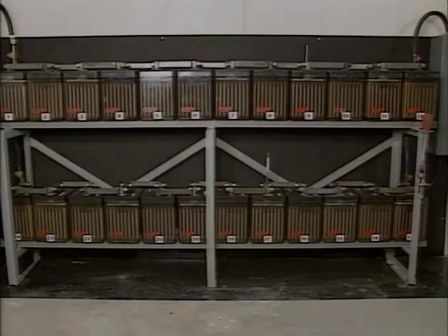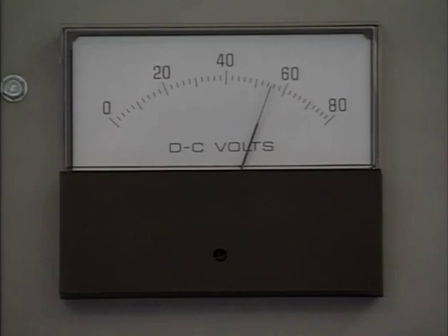As the cells discharge, sulfation occurs. The resulting sulfate crystals can be difficult to remove with normal charging and can prevent the cells from taking a full charge. For this reason, a freshening charge is typically applied to wet charged cells before they're put into service. A freshening charge is a higher than normal charge voltage that's applied to wet charged cells before they're put into service to ensure that the crystals are driven off the plates and that the cells are fully recharged.